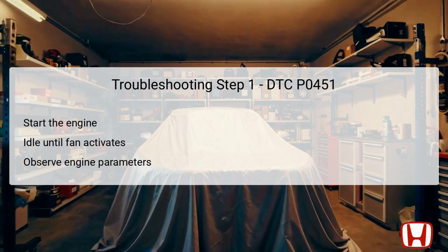Once the fan activates, it indicates that the engine is sufficiently warmed up, evidencing that the cooling system and engine management are functioning correctly. This initial diagnosis helps establish a baseline for subsequent tests and whether the FTP sensor can communicate correctly with the PCM.